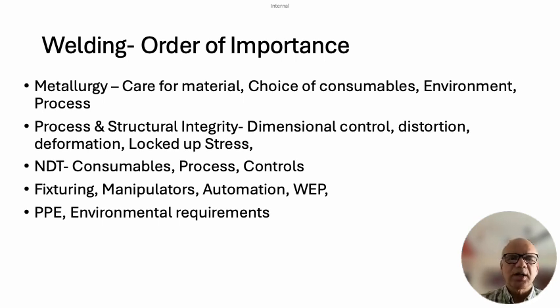The material is not that accommodative like carbon steel, where you can have as many start and end points, because of the flowability, the surface tension, the wettability of this material, like carbon steel, and to a certain extent stainless steel is good. But as you go into the higher alloying content, about 5% and above, and nickel, cobalt and titanium based alloys, then the flowability, the viscosity of the material becomes like honey.